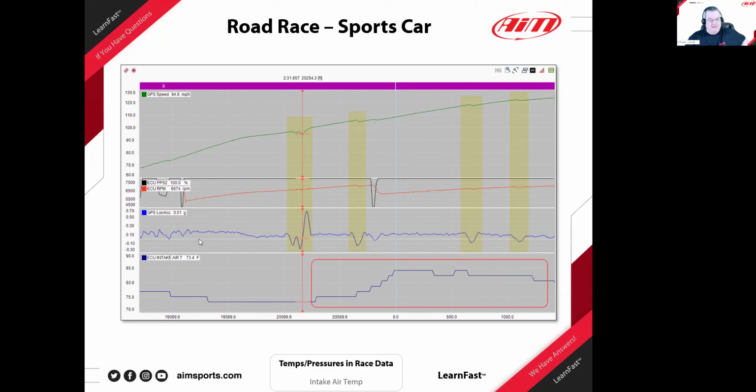And the longitudinal acceleration, if you're above the line, you're accelerating. If you're below the line, you're in braking, right? You're slowing down. The forces are such that you can make that determination. So the car is accelerating fairly well, and then the acceleration starts to drop down right here. That's the beginning of the hill, going up the hill, right? So it's not accelerating as well. And then all of a sudden we see these two big dips, sharp spikes. We're zoomed in quite a bit here.